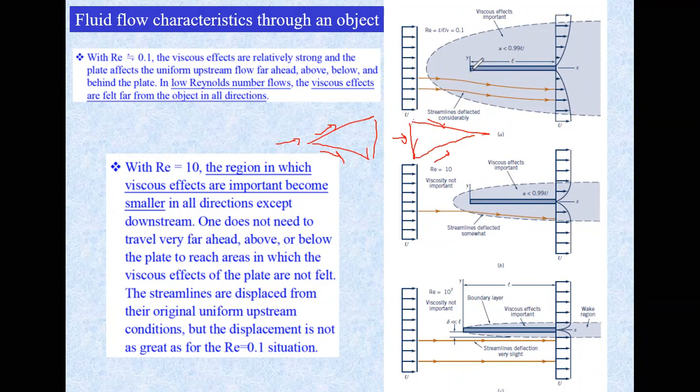So for example, in this case, if you have this shape, a small plate in the direction of the flow, then you're right. The bigger the Reynolds number, the less the shear stress or the drag for this shape, because you have a negligible pressure force.